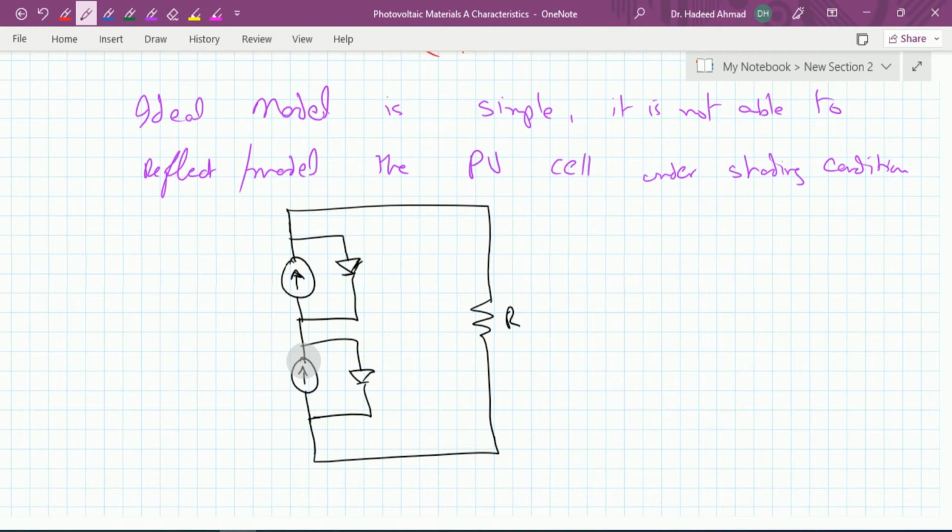So now if you see here that we have these 2 cells in series, and therefore the current through these must be the same. Let us say we have this particular cell in shading condition, which means that this cell is not producing any current, so this I equal to 0, but we do have the sunlight available on this particular solar cell, so it will be operating at this ISC value or the amount of current which is produced at a given irradiance condition.